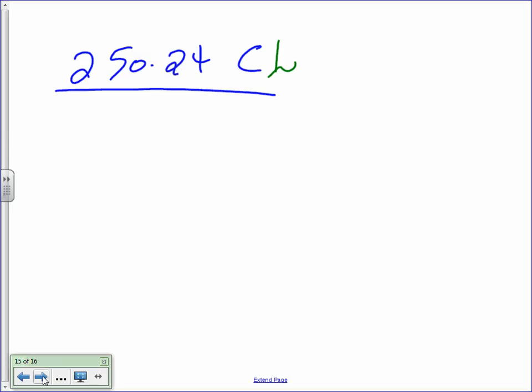For the neutral, if you look at 250.241, and you have this one in the sheet that you guys have, the code also says the neutral cannot be less than the main bonding jumper. If you go to 250.24(C), it says it can't be less than the main bonding jumper. Okay, so let's go size. Again, we're talking about the neutral here. Continue with the green here. Talking about my neutral.